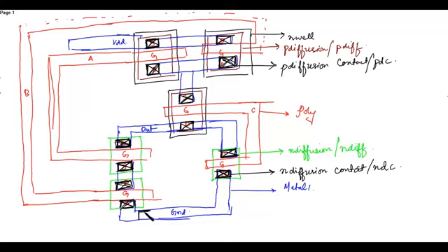Now after placing the diffusion contact, you can place the substrate contacts. These are placed in the VDD and ground layer. So this is one. You can place it as many as you want. So this is the P substrate contact. The P substrate contact is placed on the N diffusion side. P substrate contact, or you can term it as P well contact, PWC.